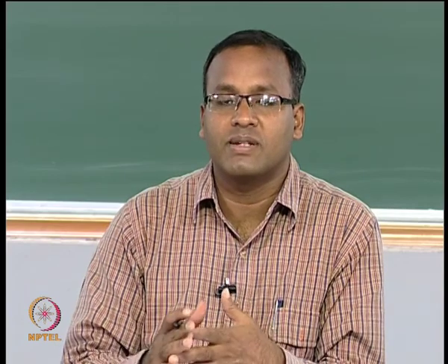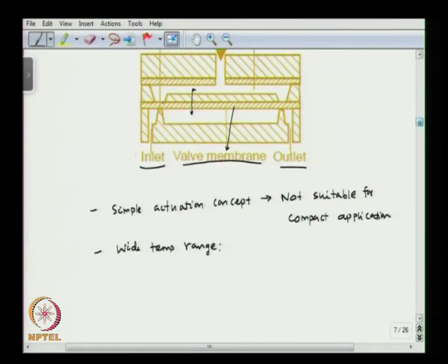This is because when you apply a pressure, irrespective of the temperature, the membrane is going to deform. So, these pneumatic microvalves will have a wide temperature range. This is because the membrane deflection occurs irrespective of temperature.